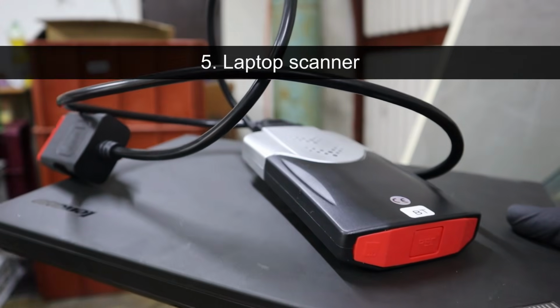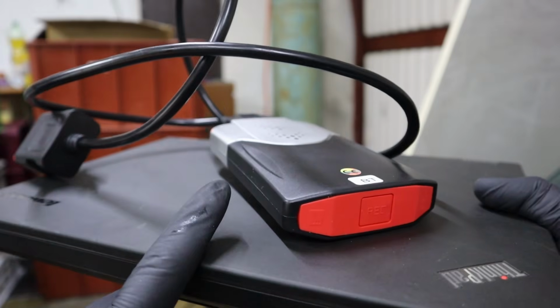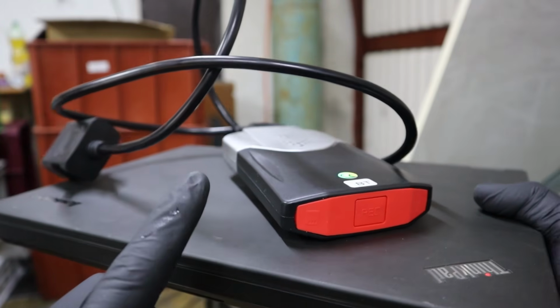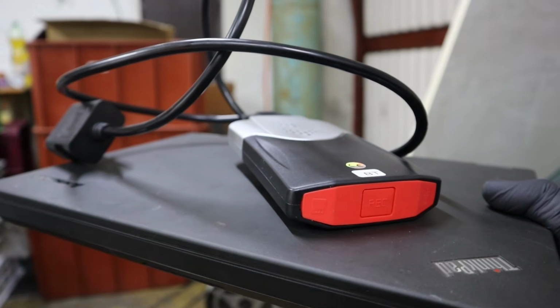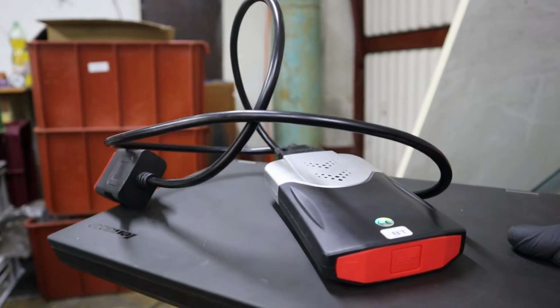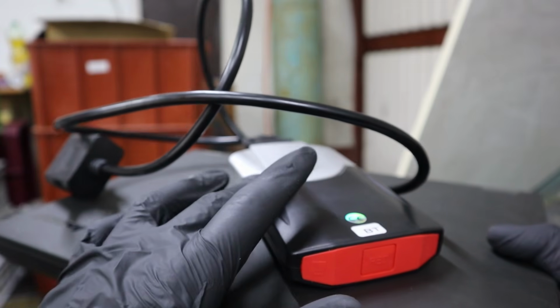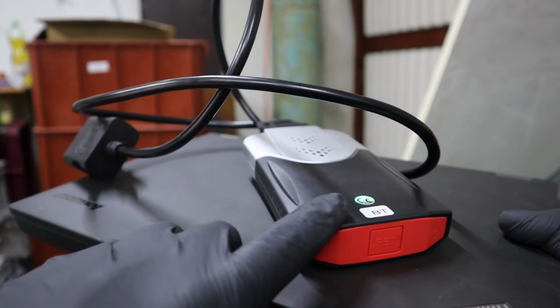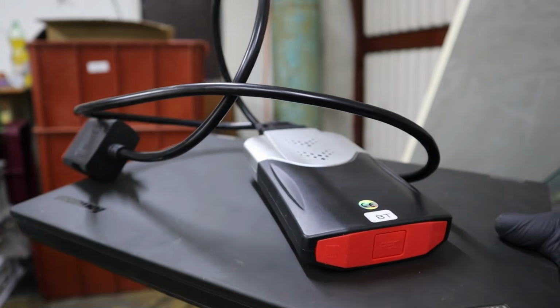Another type is the laptop OBD scanner. Also they can have really good value for the money, but the downside is you will have to get a laptop. I don't recommend using your main laptop because you can get it damaged easily. I mean, in the garage you can see how the laptop can get damaged, and also a lot of this diagnostic software comes from AliExpress, and to install a lot of them you have to disable your antivirus, and you don't want to risk that with your main computer.